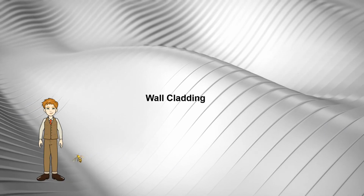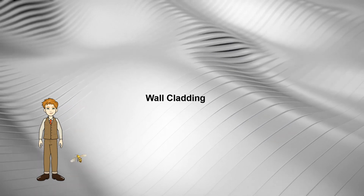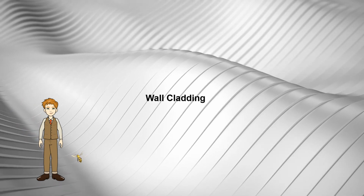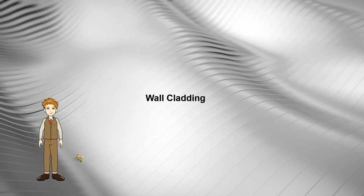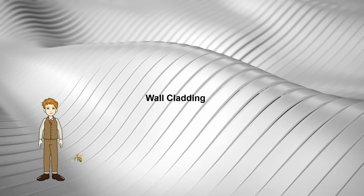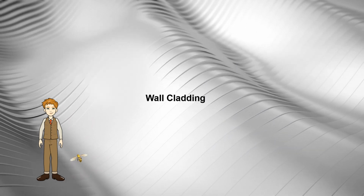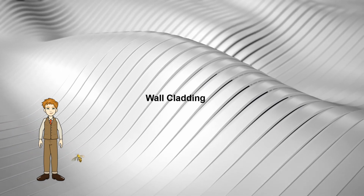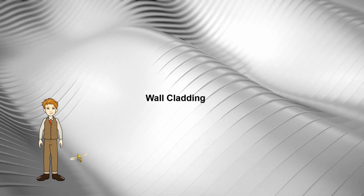Wall cladding. The systems used for walls are similar in construction to those for roofing. Since the sheets will normally be vertical, the weatherproofing requirements are less rigorous. Another important difference compared to roofs is the lower angle of incidence of the sun, allowing the full range of colors to be used without excessive surface temperatures, so giving the architects the widest possible scope for creative use of color.